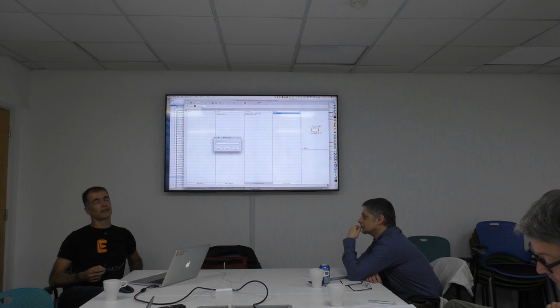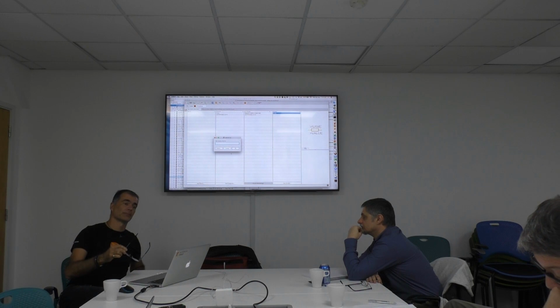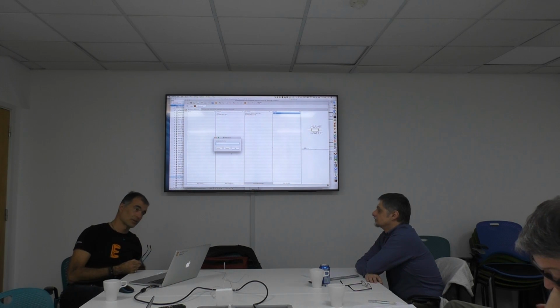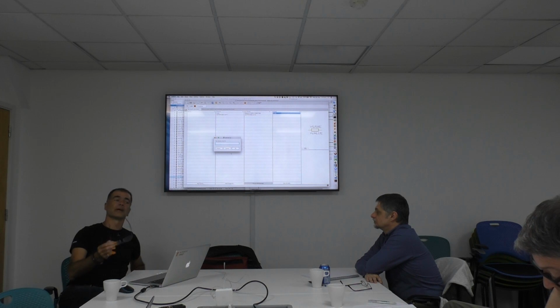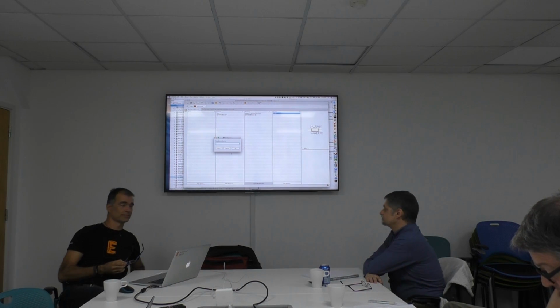There is also an option to create the device first: I must have a symbol before, I add my symbol, and then in the device editor I can import a package from anywhere. That's also possible. But my preferred way is first the package, then the symbol, or first the symbol, then the package, and the last step is the device.